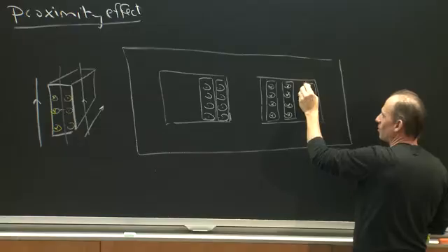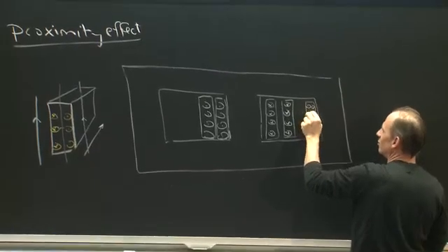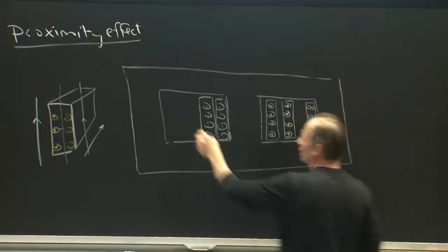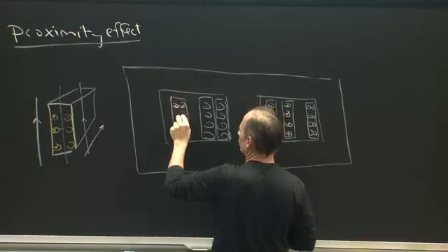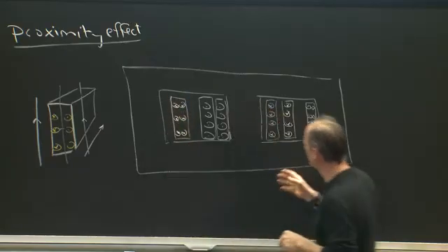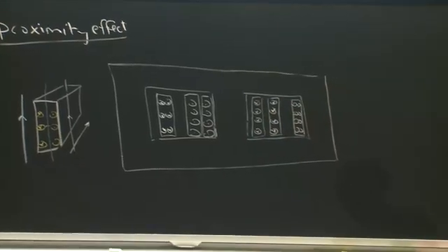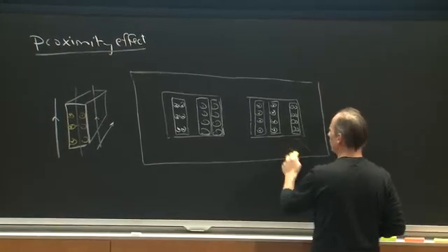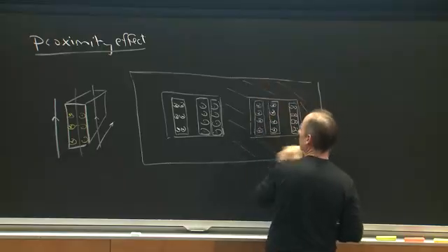It's a 2-to-1 transformer, so here I have two dots coming out, two dots coming out, two dots coming out, and same thing on this side, two dots going in and so forth. I'm plotting the current density, and these are the net currents being carried. So what happens? Inside my core, if this is high permeability material, there is no H field.